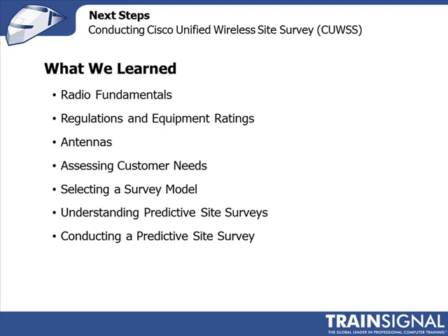of those spectrum regulations. We then went on to talk about antennas, talked about the basic concept of antennas, starting with the isotropic antenna. We talked about when do you use external antennas with your access point versus the internal antennas? We discussed MIMO. What is MIMO? We talked about multiple spatial streams that leverage off the multipath environment. And we did a demo showing the impact of antennas on coverage and capacity. And we took a look at the impact of antennas on your coverage.